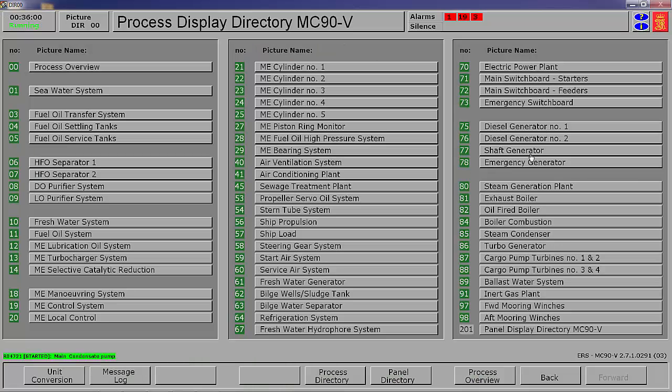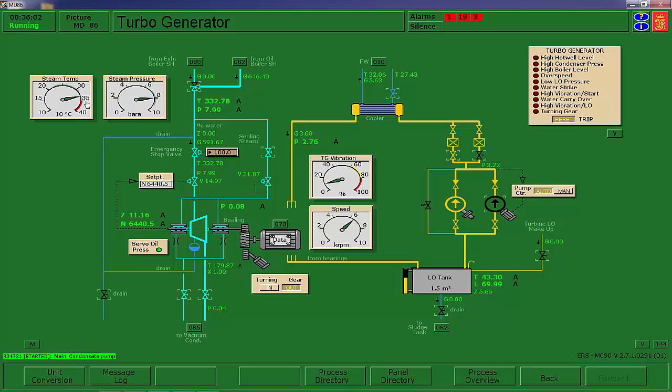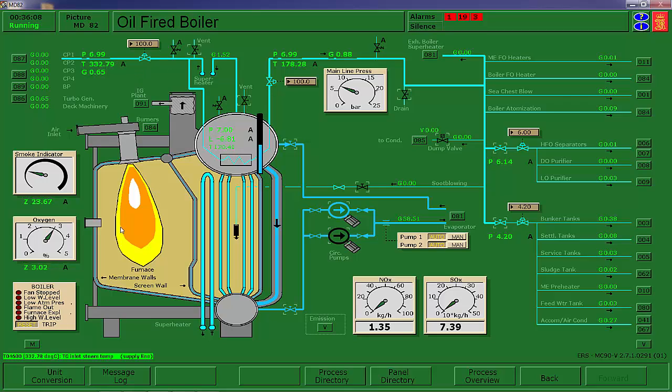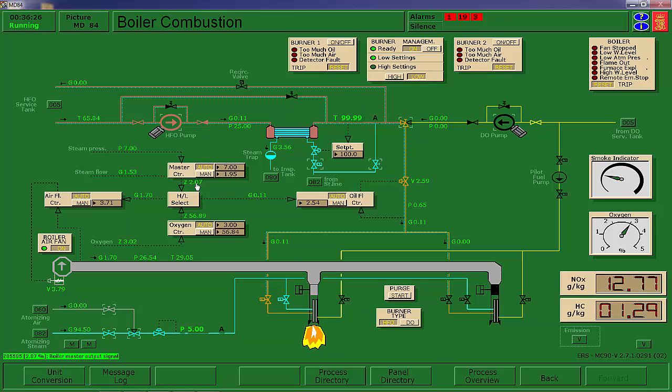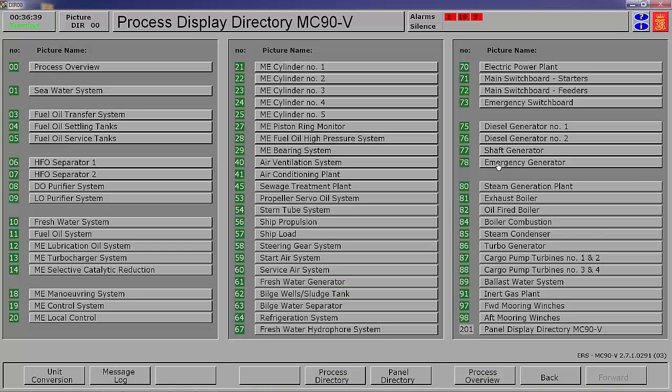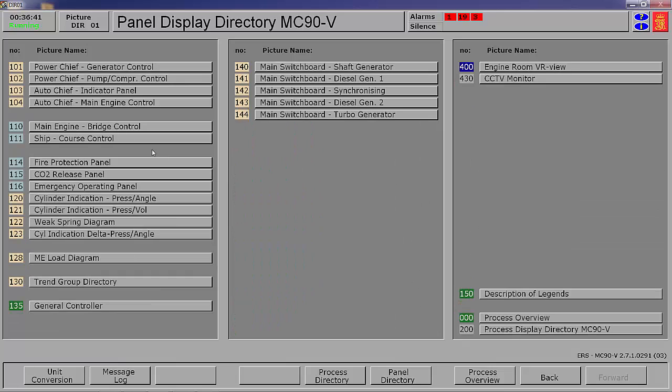Now, I want to bring up too that it's showing a little bit high on my steam temperature. Now, what's going on is there's not a heck of a lot of flow right now through that superheater. But I want to point out that we are at a very low firing rate, 2%. Right? I mean, this thing is barely idling. This is about as low as you can go on this boiler. It's barely bubbling. So I'm not worried about that superheat temperature. I think that is normal and is not a problem.